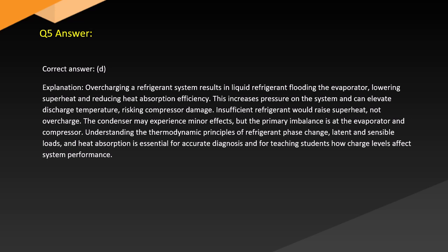Answer. Correct answer, D. Explanation. Overcharging a refrigerant system results in liquid refrigerant flooding the evaporator, lowering superheat and reducing heat absorption efficiency. This increases pressure on the system and can elevate discharge temperature, risking compressor damage.